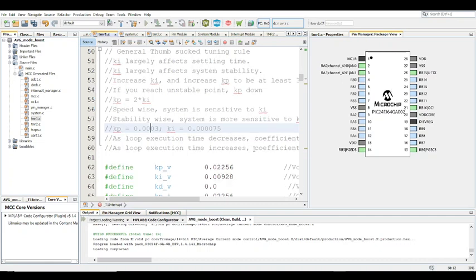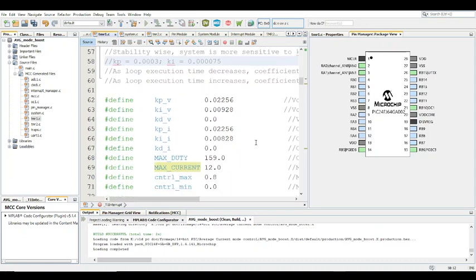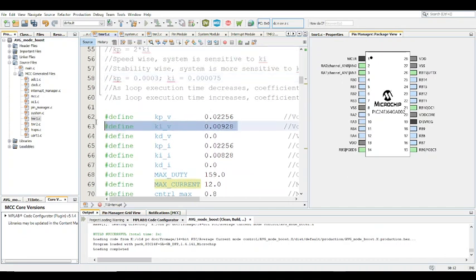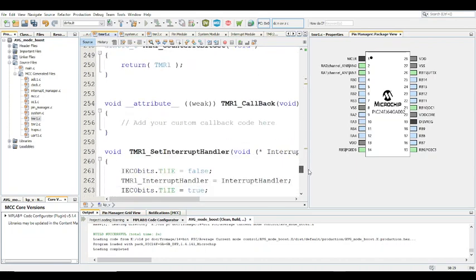But it does get to the set point, giving yourself a stable baseline to go off from, which is a good thing. And always start from the KP of the output, the outer loop, and its coefficients from this point. You don't want to make your inner loop unstable, if you've already proven it to be stable.